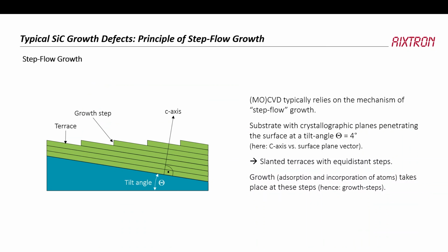One thing about the growth of silicon carbide, well, first of all, it's step flow growth, just like with many of the semiconductors that are grown in CVD or MOCVD. So we have a terrace, and we have this step, and we want the atoms to actually migrate all the way to the step and then continue the growth in this direction. So the growing crystal actually takes what it sees at this edge as a template to continue growth.